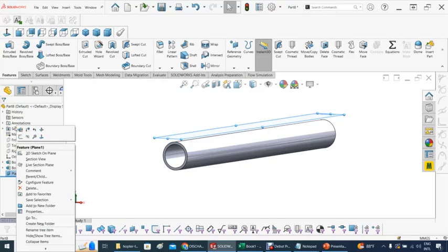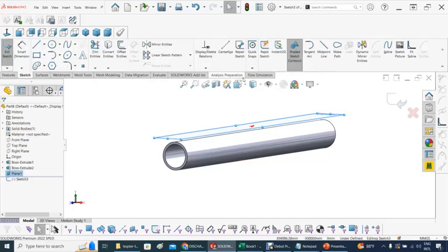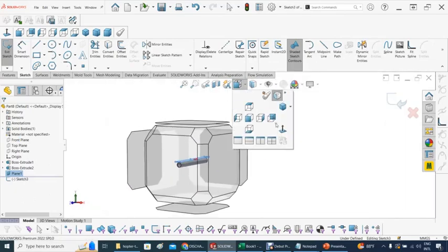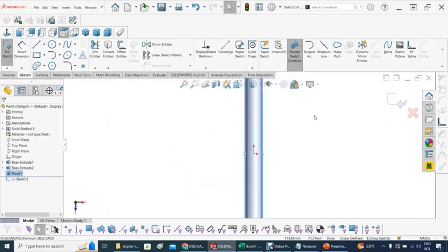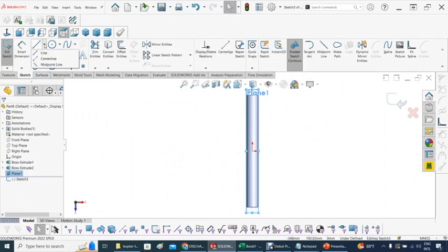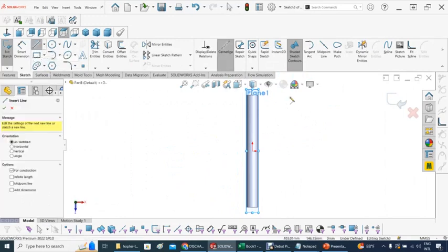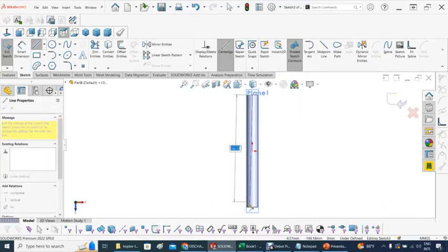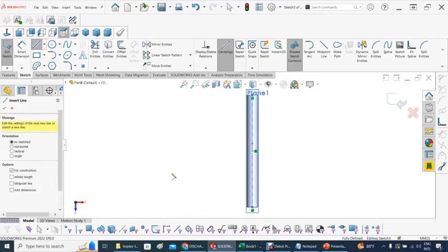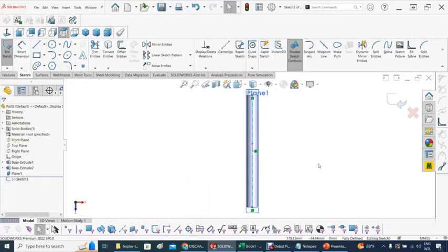So we're gonna create a sketch, and on that sketch, let's put that in front of us so we know what we're doing. And here's the story. We want to create a center line to align our tabs the way we want them. So from there to here, that's our center line. Escape from here, and now we want to create two circles at a certain distance.